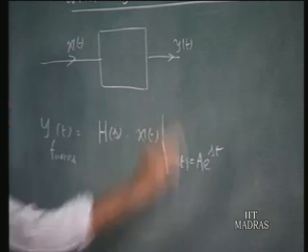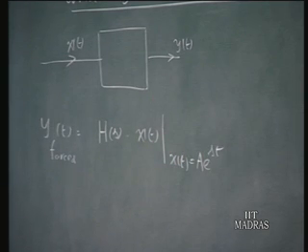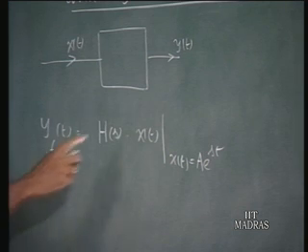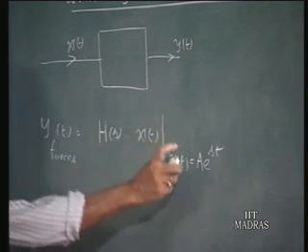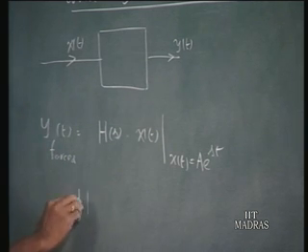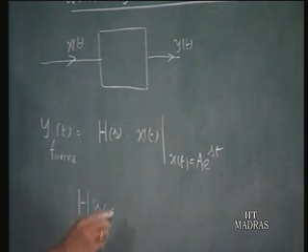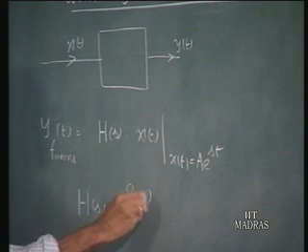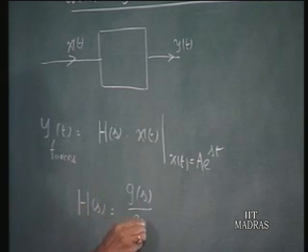This is the summary of what we have discussed just now. This proportionality is valid only when x(t) is of the form A e to the power of st, not for other signals. That is important. And secondly, we saw that H(s) is the ratio of two polynomials in s, G(s) over F(s).